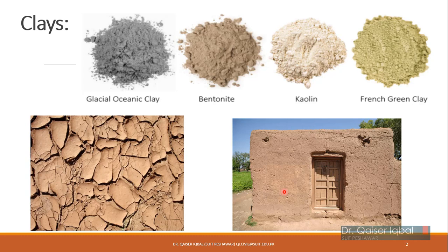However, clay is commonly used. We even make houses with clay in villages, and you can still come across old constructions made of clay. So clay is commonly used in various engineering activities. Previously they were used for construction of houses. Nowadays they are used as a filler material in roads. They are also used in the construction of bricks. Clays are also used in the clay core of dams for prevention of moisture transfer, because of their very low moisture transferability. Their permeability is low.